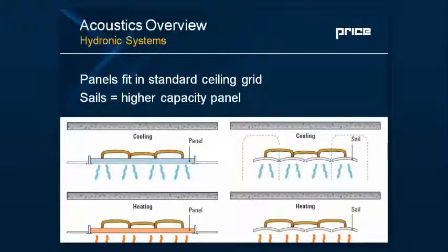You've also allowed yourself to take advantage of natural convection, where the air is rising, you're getting the buoyancy, and then once it comes in contact with the cold heat exchangers above the sails, that dense air drops back down. These are great for a variety of climates, and you can have these in both hot and cold applications. And instead of using air, you're using water, which is more effective.